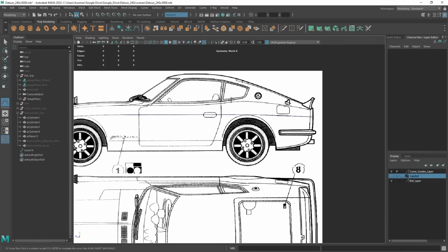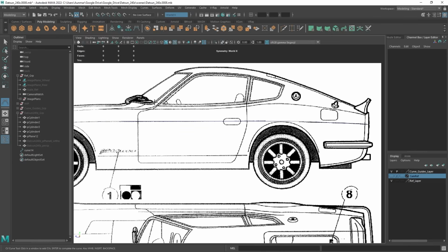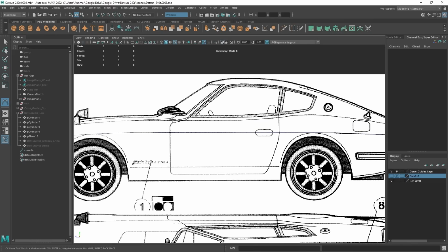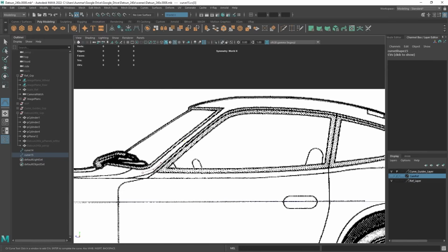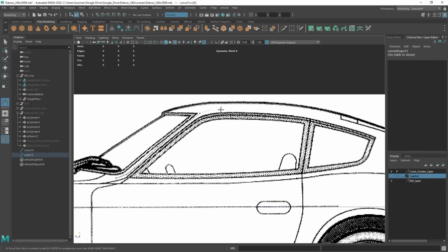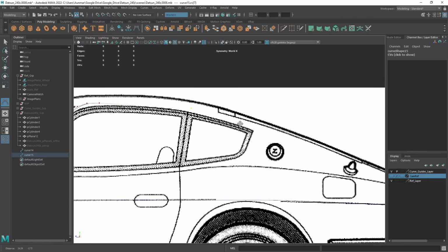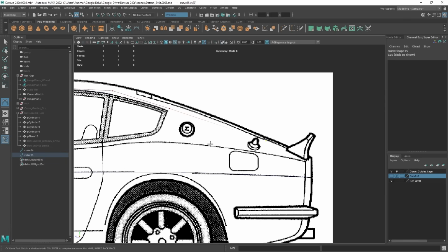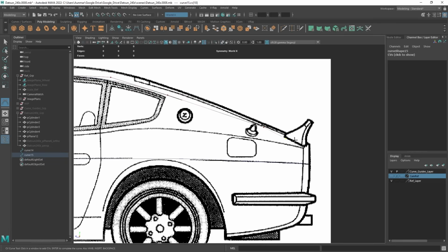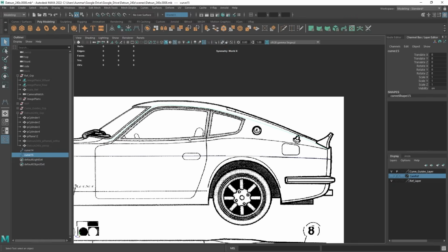So what I can do now is let's maybe start from the end of the hood to the roof, to the rear. So if I go here and I left click, I'm just going to left click 3 times, anywhere I have some good curvature, and up here, and we're just making our way around. And this is going to be the main top piece of the vehicle, and we'll end up right here. Okay, so I hit Q to exit the tool.